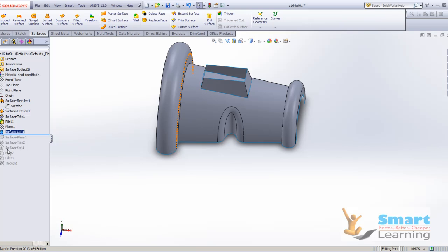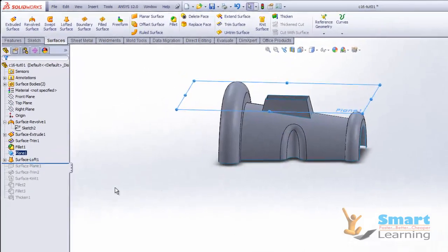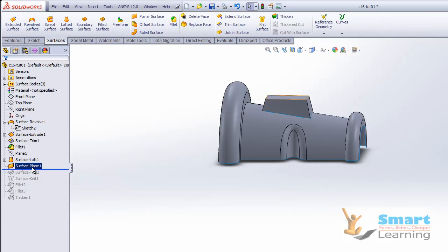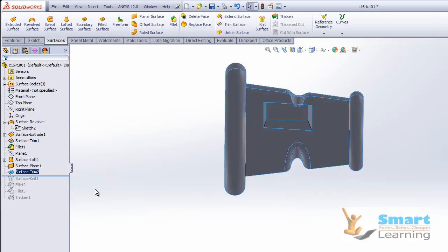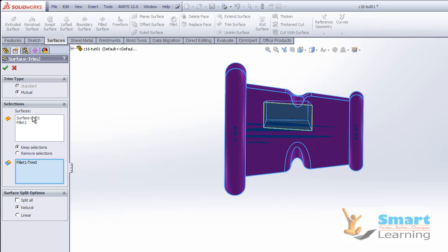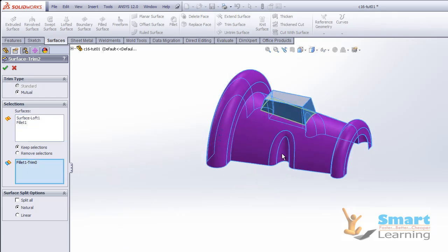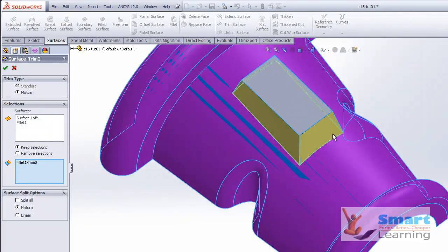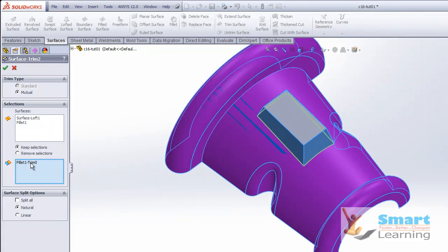And you can use both the surfaces. So over this particular plane, when you are going to create this particular sketch, then you can project the 2D curve which already you know how to project. And then you have to patch this, and finally you have to go for the surface trim. So when you are going to trim this, this will cavitate. So this is the surface and this is the particular item which you are going to select, and that will trim it.